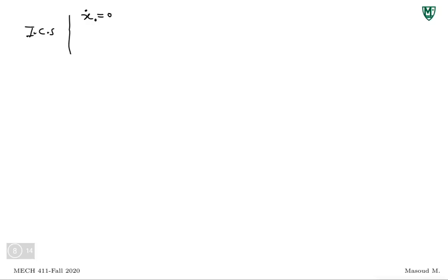Now, when this pump is sitting on this beam, obviously we're going to have some initial deformation. Think about this, m, and then this is k. So wherever this beam was, we're going to have some initial deformation because of the weight of the pump. And that initial deformation would be the initial displacement. Tricky, right? How do I find that initial deformation, which is going to be the initial displacement for my system? Well, I know the stiffness. F is equal to k x naught, or W in this case. Let's just write it in the general form. F is equal to k equivalent x naught.